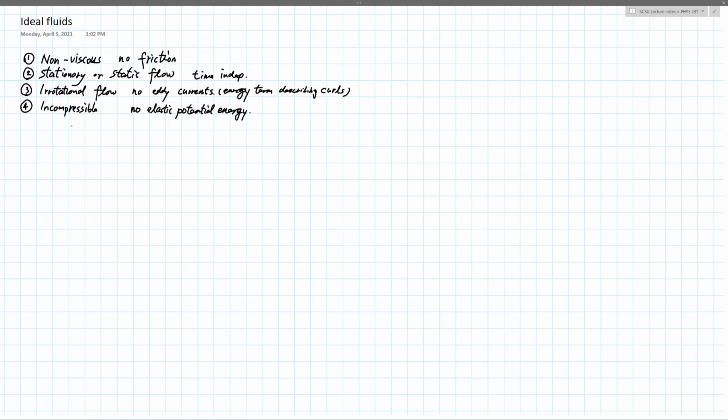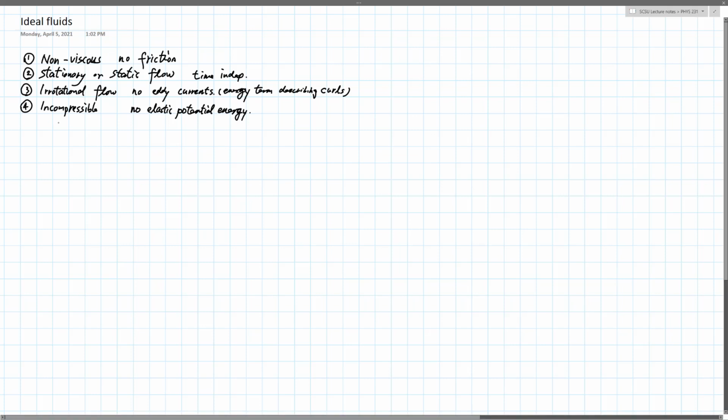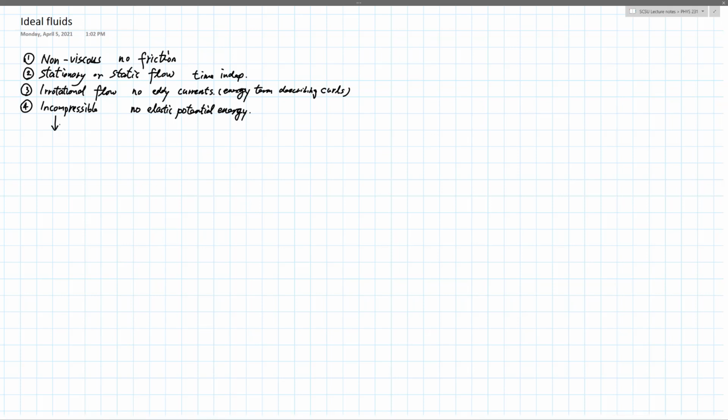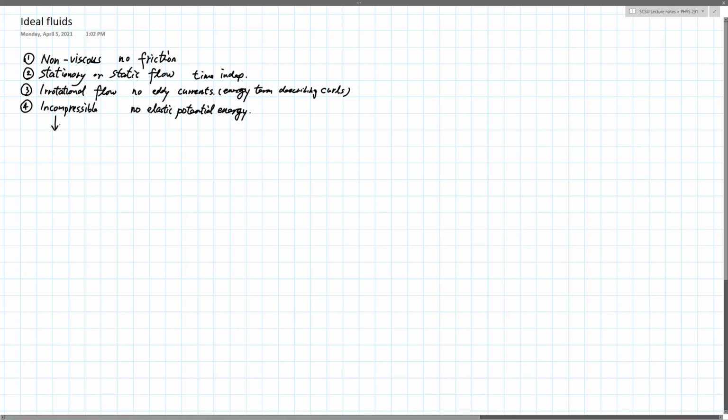And ideal fluids, especially the incompressibility, give us a mathematical expression. So this thing that I wrote last can turn into an equation. The equation will say that the same volume into a certain tube or structure will come out as the same volume from the other end. So if you have, for example, a reducer, it reduces the diameter of a pipe, let's just say from 2 inches to 1 inch. I'm just making it up.